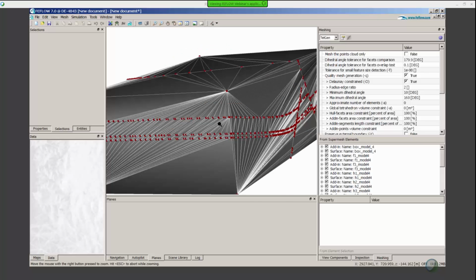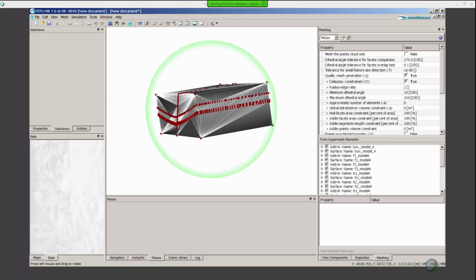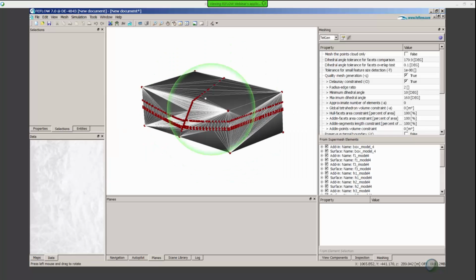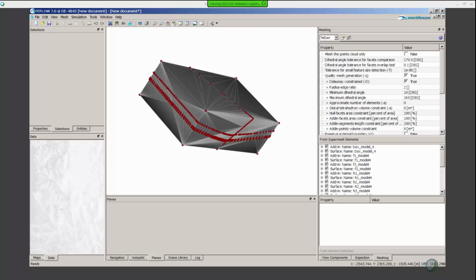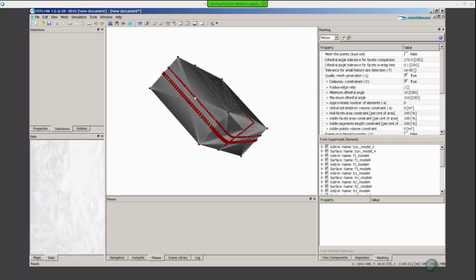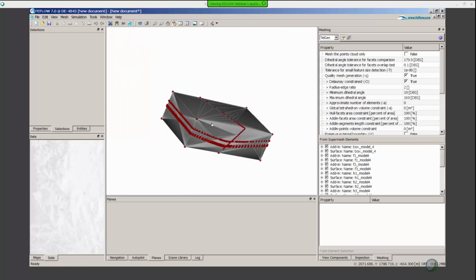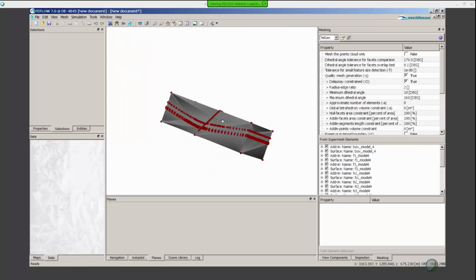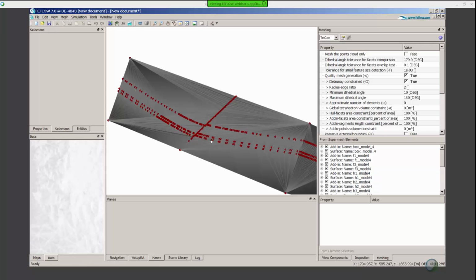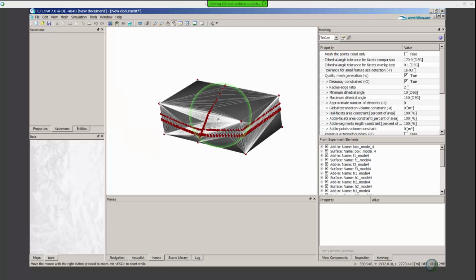So this is also a point that you have to take care of. If you have very complex triangulated surfaces, this will also control the quality of your mesh. But we have possibilities to remesh the model domain again, so you can always end up with quality meshes from our tetrahedral mesh generator.